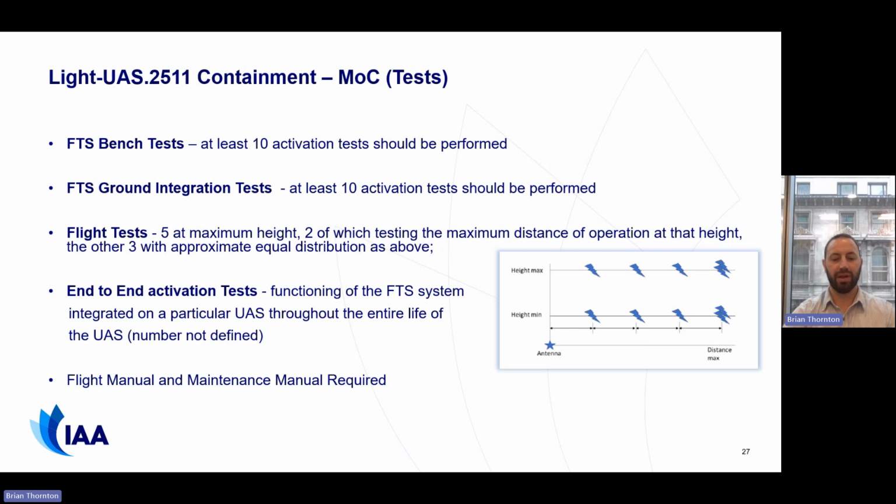MOC 2511 prescribes that the flight termination system manufacturer, developer, or OEM needs to test that flight termination system for the entirety of its life until failure. All of these tests must be available and presented to the competent authority to show compliance with MOC 2511. And also in all that, a flight termination system manual needs to be provided to an operator who might purchase or procure one of these flight termination systems, prescribing flight system integration, but also potentially prescribing maintenance requirements for the flight termination system.